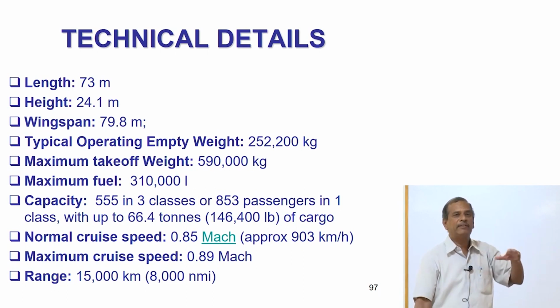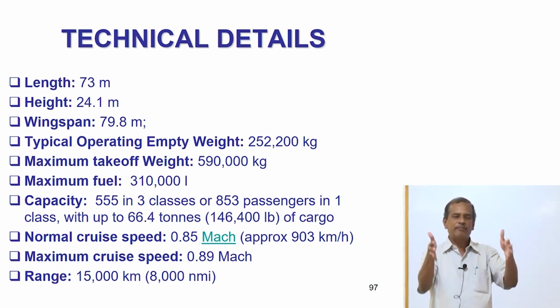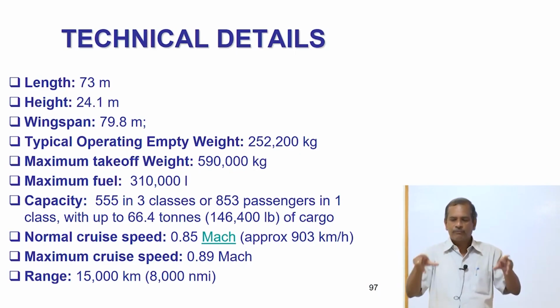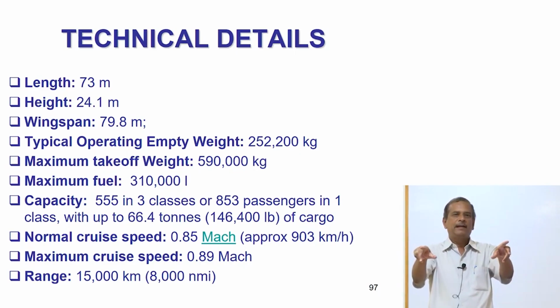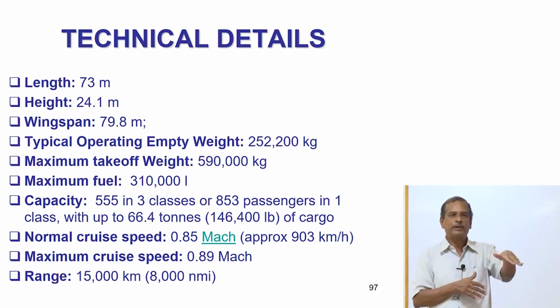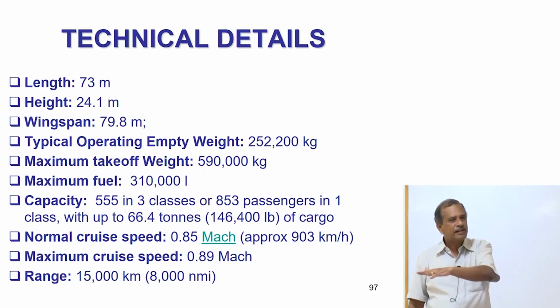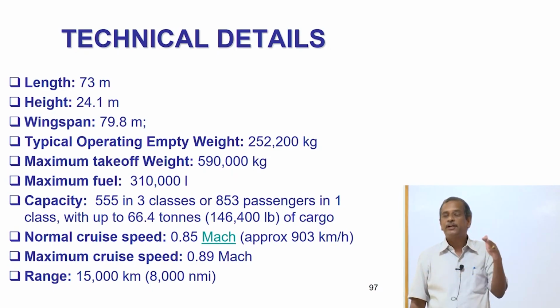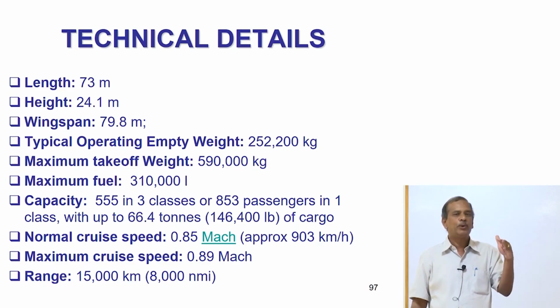So unlike a highway where the traffic wanders, in the case of a runway pavement, they follow a particular path. So wheel rutting will be along a particular path. The duration of the load application on a runway is only a fraction of a second because the aircraft lands at 200 to 250 kilometers per hour. But it reduces speed when it goes to exit taxiways and crawls at a low speed in a taxiway. So the deterioration in a taxiway will be more than the deterioration in a runway. So how do I design a sustainable taxiway? What material, what type of pavement, what combination of different layers is again a challenge.